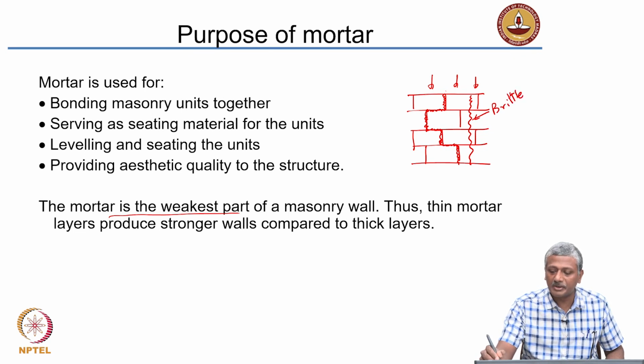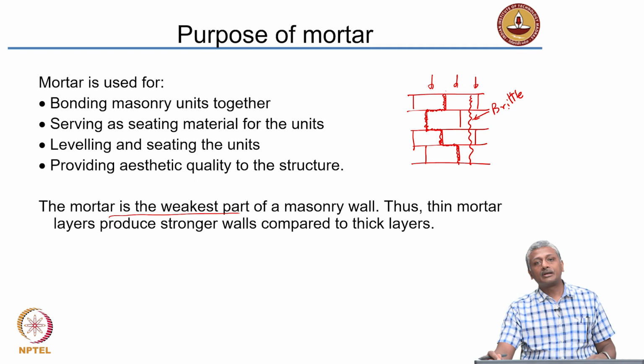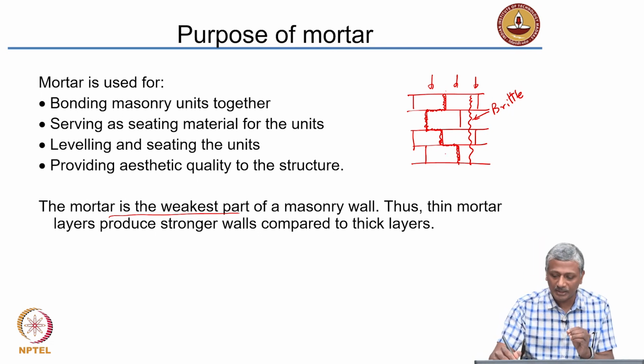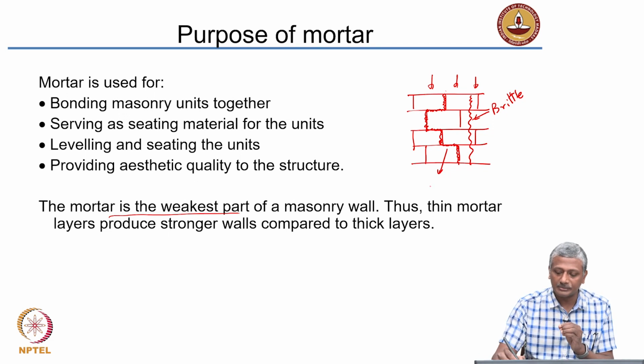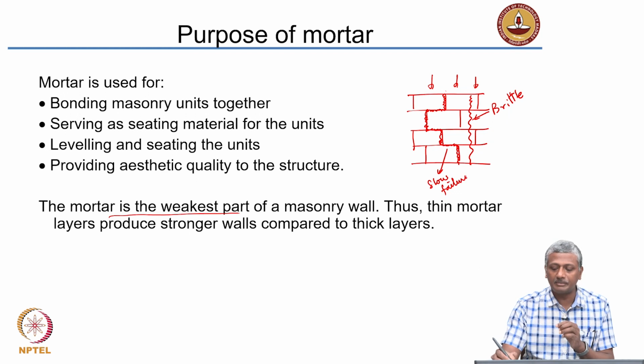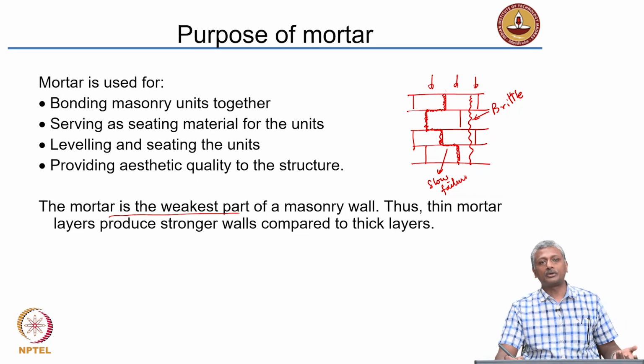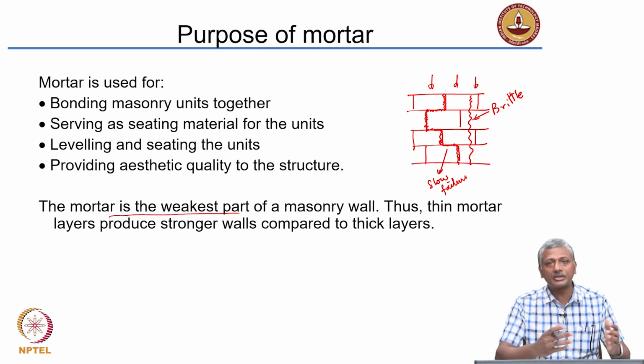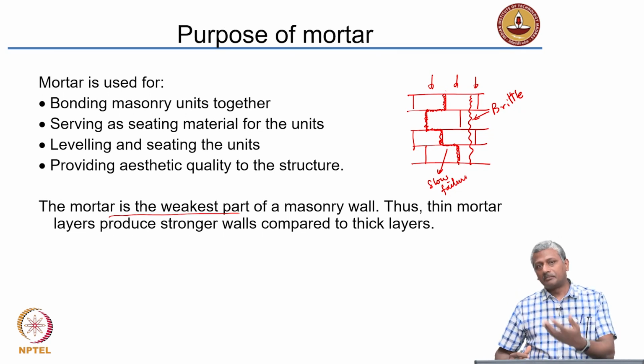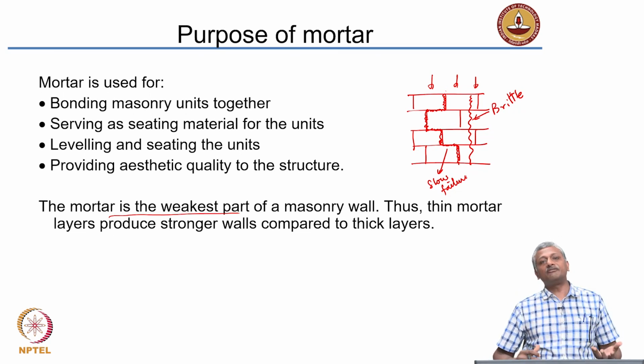In such cases, in a brittle failure, your structural collapse will be sudden. And in engineering buildings, you always want to ensure that you have a slow and steady failure. So, that is what you get when the mortar is weaker, you get a slow failure. May not be a ductile failure, but you will get a slow failure. Not like metals. Ductility in metals is a completely different order. So, here we are talking about slow failure which gives signs of damage so that people can be evacuated from the building. But a brittle failure will be a sudden failure.